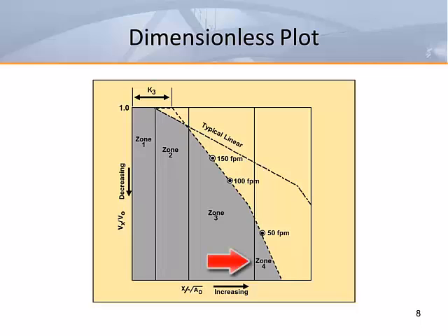The fourth zone is relatively low velocity. The performance in Zone 4 is a function of CFM. The performance is independent of outlet size. Radial diffusers operate in Zone 4.